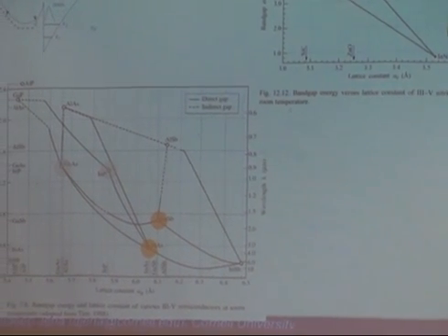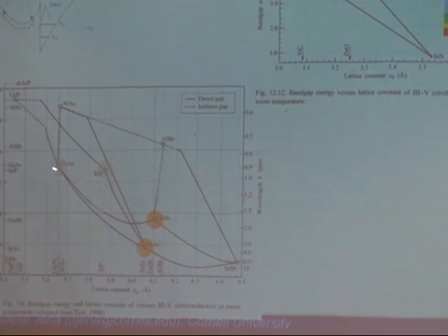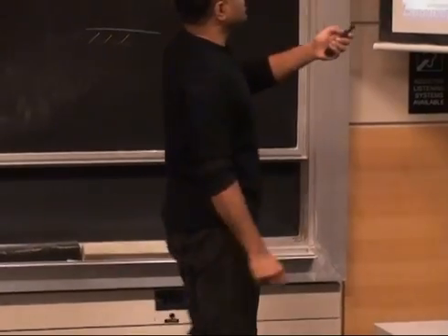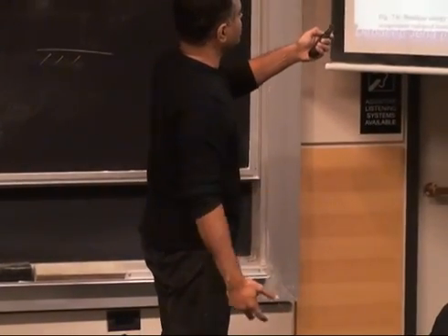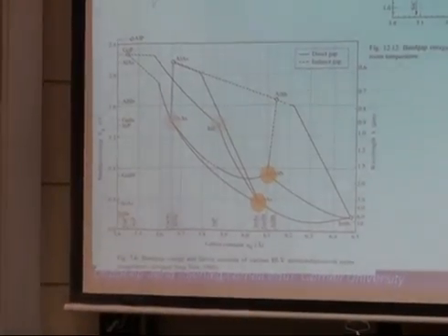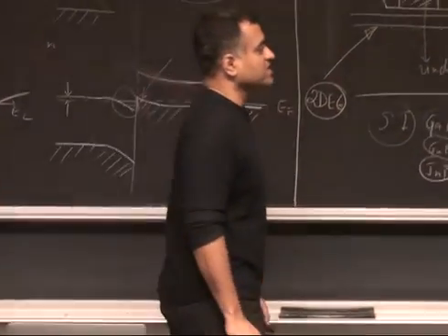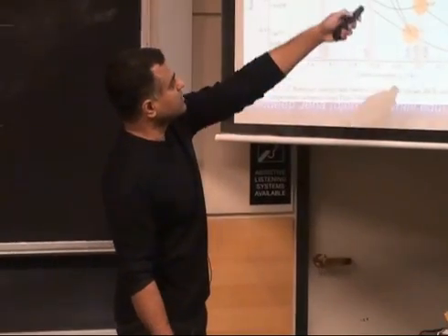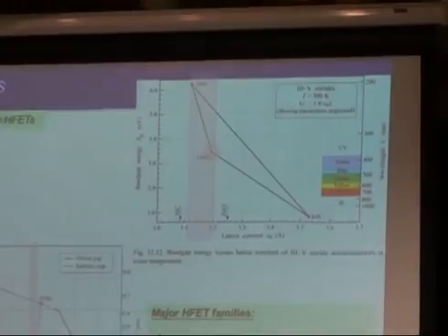Based on this idea that we kind of pointed out, because of these requirements, HEMT technologies have been developed for gallium arsenide, for indium phosphide, for gallium antimonide, and indium arsenide. These are the material families for which HEMT technologies have been developed today, and then obviously a big new one, which is gallium nitride. So these HEMT technologies have been developed for all.